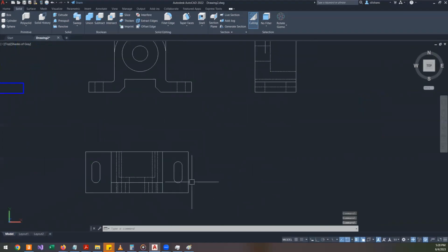That is up to you. The problem with the flatshot command is once you generate the view, that's it. After that point, it is all your responsibility. How to align it, how to rotate it, the software does not give you anything.